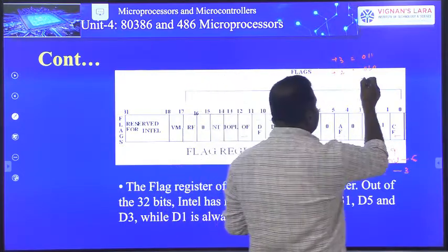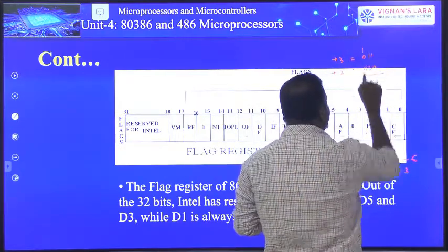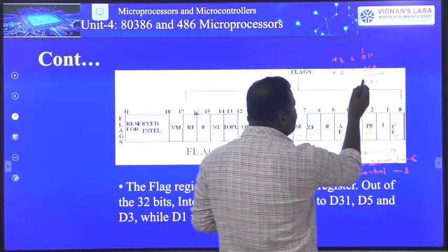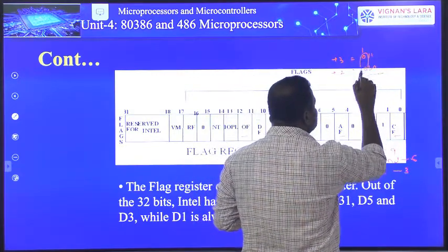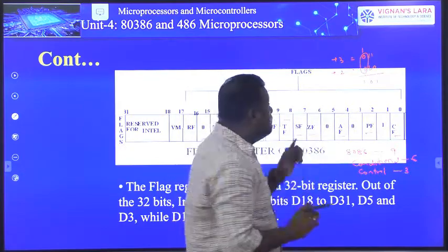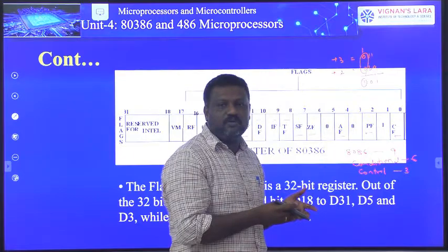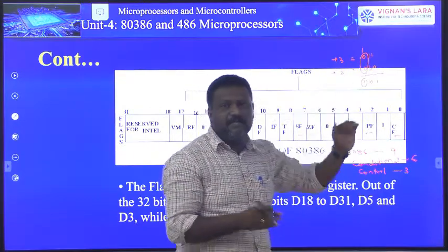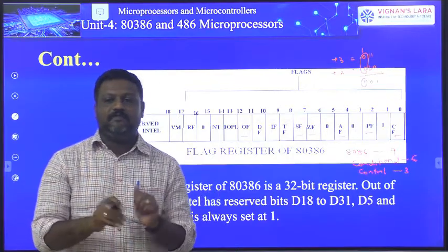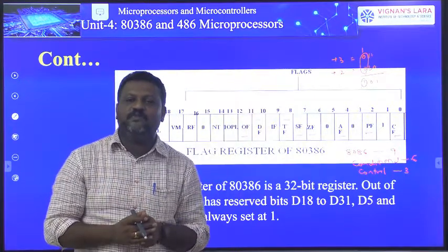So if I do the addition, sum 1, sum 0, carry 1, and here sum is 1. So here what happens? Your input number sign is 0, that means the input numbers are positive, but the produced result sign is 1, meaning it is negative. Once this happens, we can say that the produced result has overflow, because this addition satisfies the overflow rule.